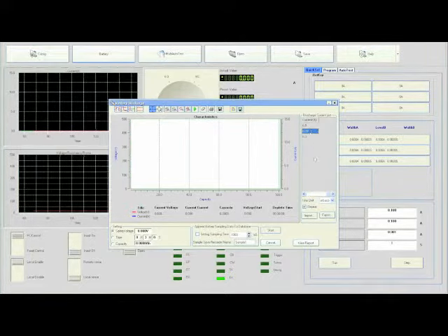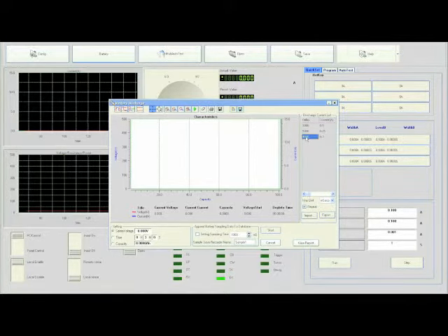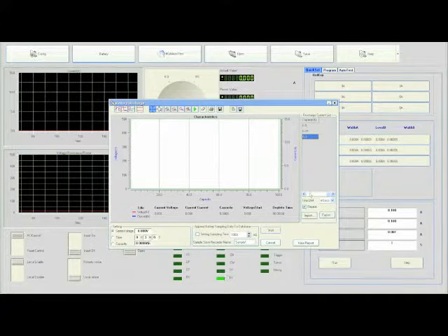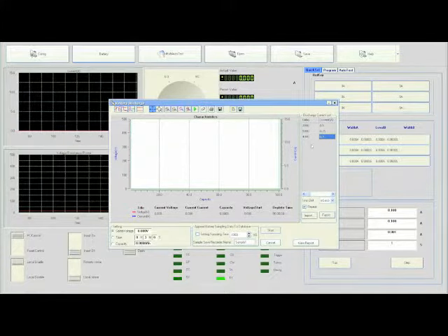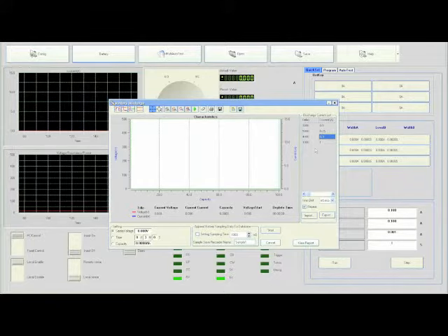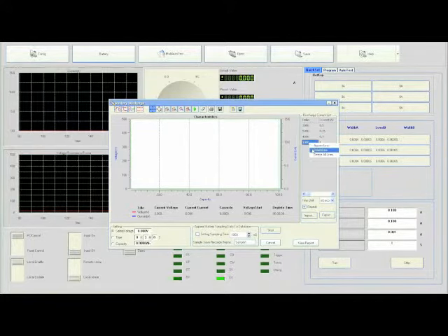Lastly, enter 4000 for delay and 0.3 amps for current. If more values are needed, simply right-click somewhere on the list box and select Append Line. To delete an entry, select the entry to delete. Right-click and select Delete Line.